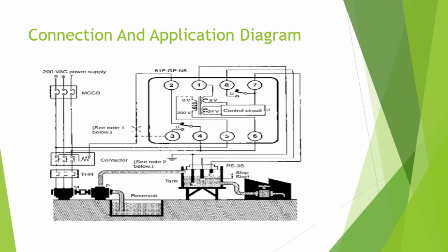The MCCB, the molded case circuit breaker, is used here, and after that the contactor and thermal overload are used for the protection of this motor pump. So this is the part of our desired floatless level switch relay.